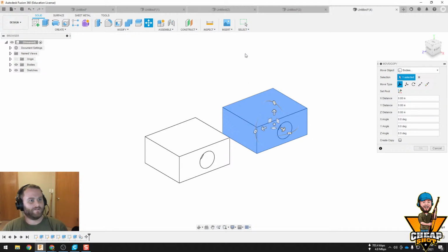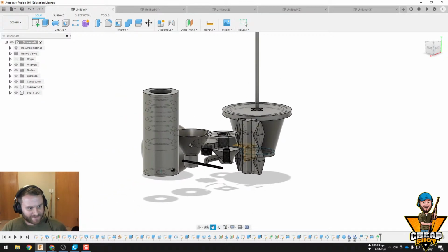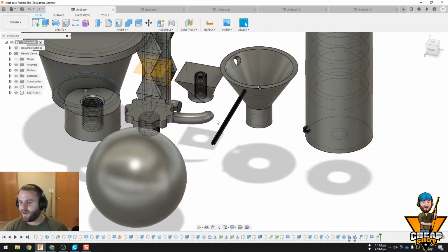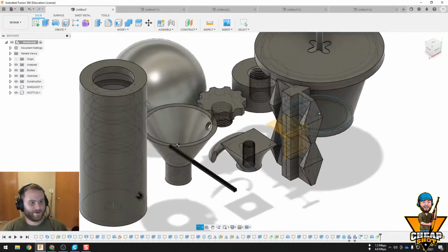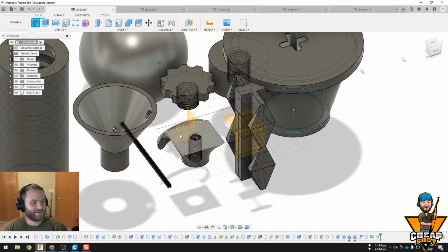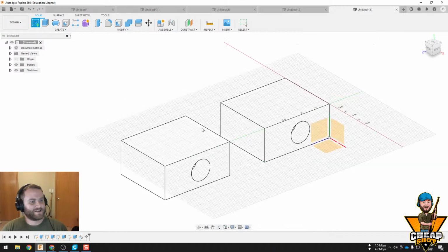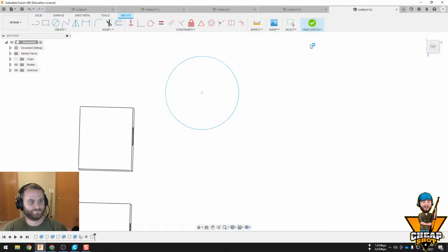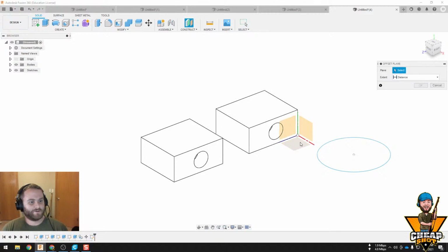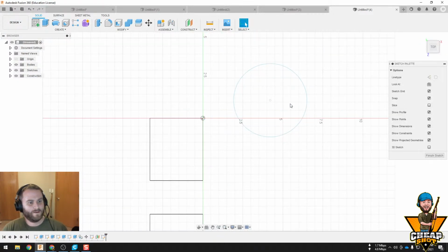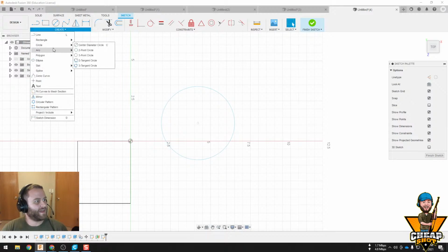Aaron, I'm telling you, a blended sweep in Creo, right? Here, I did that. Look how easy this is, my friend. This is how easy a blended sweep is in Creo. I do a circle, I create my offset plane, I can do whatever I want.